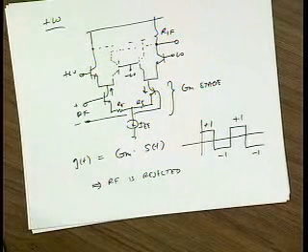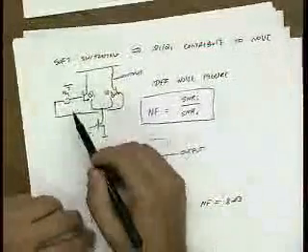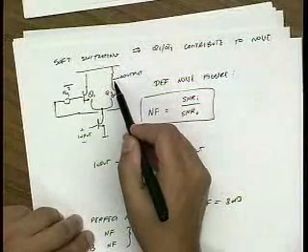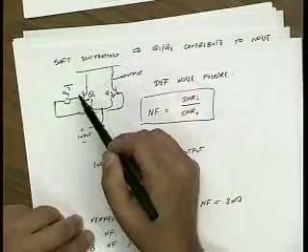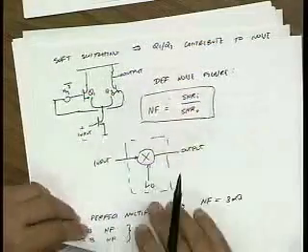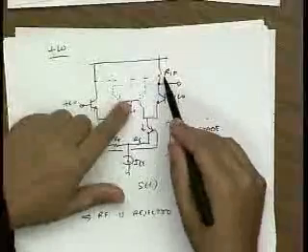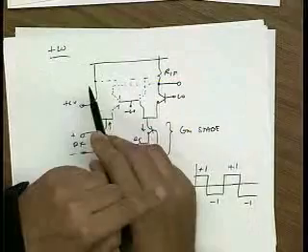Okay? Now let's see how the LO is rejected. Okay? In the single balanced mixer, let's go back a few slides. This differential pair takes my LO drive and just gains it up to the output. It's not rejected at all. It's only rejected by the output filter. Okay? So the LO signal actually modulates the output. In a double balanced mixer, the LO has two paths. It has this path to the output and this path to the output. And these two paths are wired up in an opposite direction.